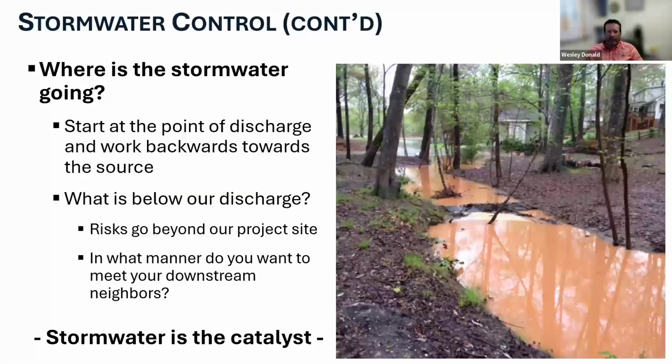So again, where's stormwater going? A lot of times when we talk about inspecting sites, good practice is to start at the discharge point and work backwards towards the source, and look at all the things that are happening along the way to determine what we are doing well and what our deficiencies are.